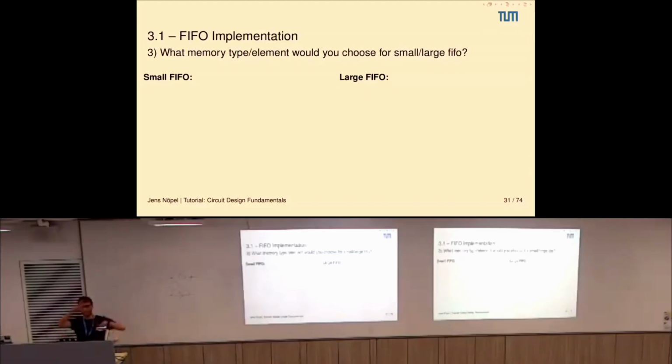So they're not widely distributed over your chip, but come in array structures with sense amplifiers to read them and so on. And a latch and also flip-flops don't need additional read sense amplifiers, so it's just a different building block.